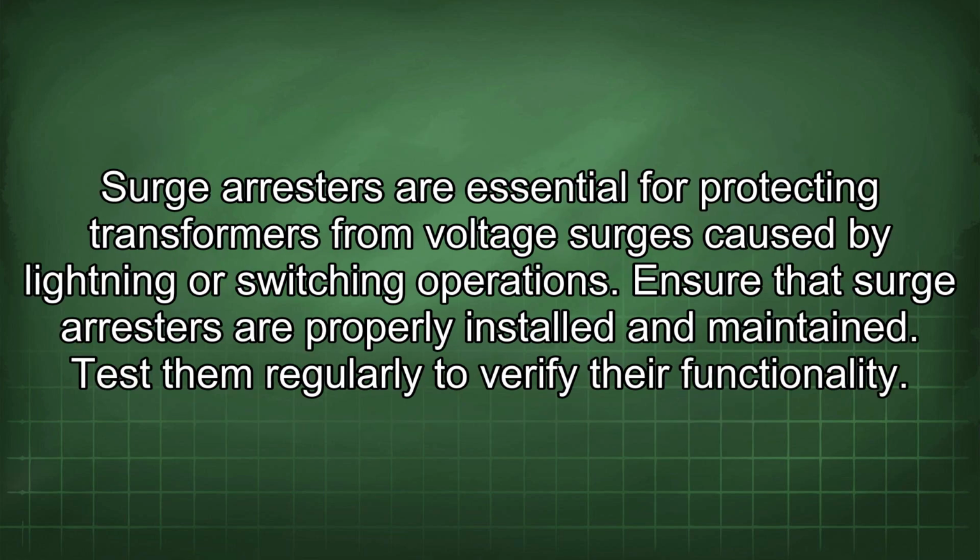Surge arresters are essential for protecting transformers from voltage surges caused by lightning or switching operations. Ensure that surge arresters are properly installed and maintained. Test them regularly to verify their functionality.